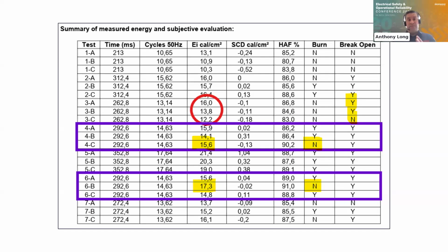And every time we test fabrics, we can test them on simultaneous days and we will get different results out of the same batch of fabric. And when fabric is produced, it's also produced within tolerances of weight. So each of those fabric weight tolerances will also lead to an unpredictability. So the 50% probability is what we always advertise because we know the probability goes into the arc flash testing itself, and into the actual production of the fabric itself. So we're looking at the 50% probability.